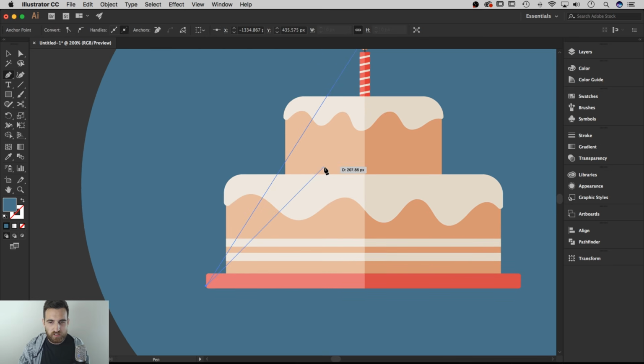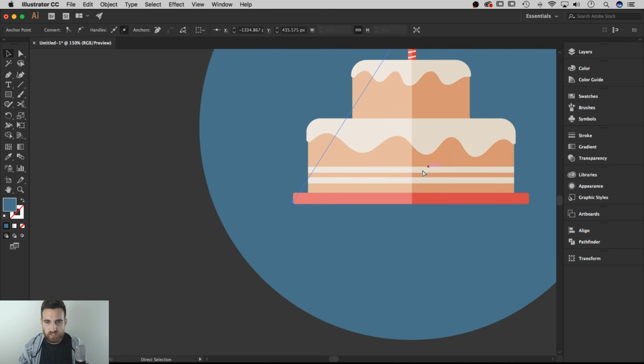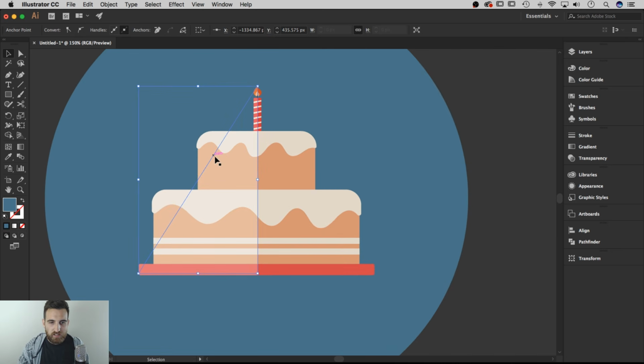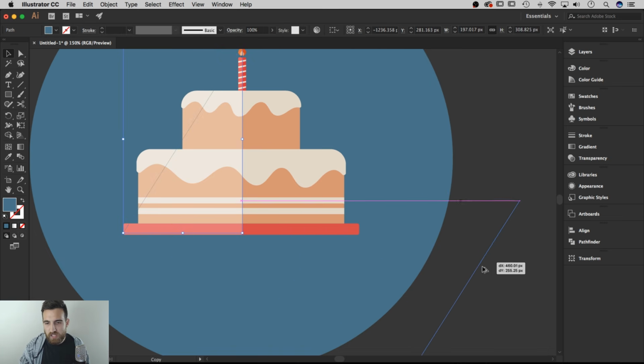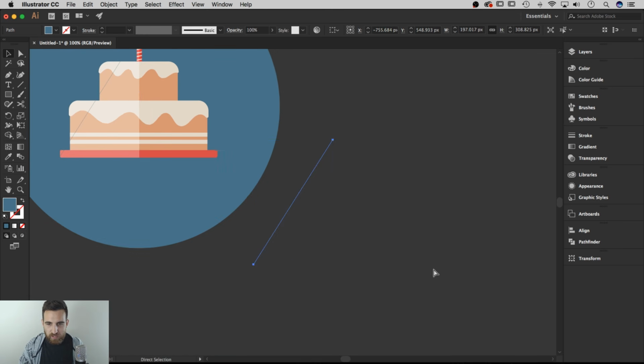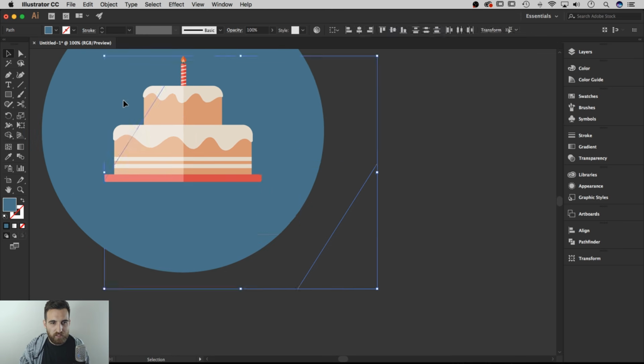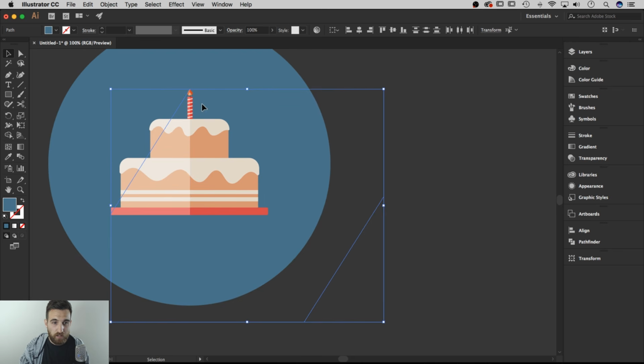I'm going to switch back to my selection tool. Shortcut key is V. And with this, I want to duplicate this out. So I'm going to have that selected, and I'm going to hold Option and duplicate it outside of our circle background. And once I have that, I basically have 2 objects now. I've got these 2 parallel objects. That's the most important part right now, is that these 2 are parallel.